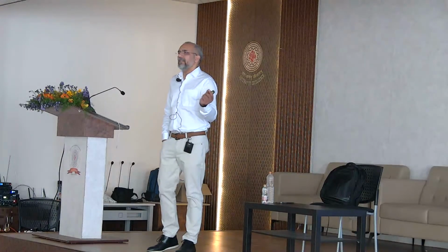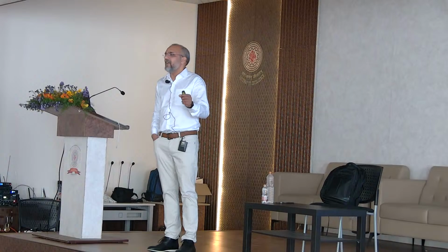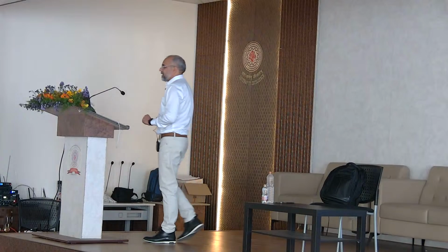What they did was use simple tape, put graphite on the tape, and repeat this multiple times. Finally they ended up with a single layer of graphene. But that was a very hard task, because on the tape somewhere you have a single layer, somewhere a double layer or multilayer. So it was very hard to locate the single-layer graphene on the substrate and fabricate a device.